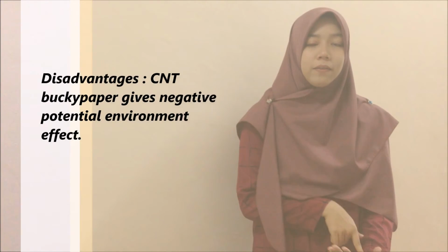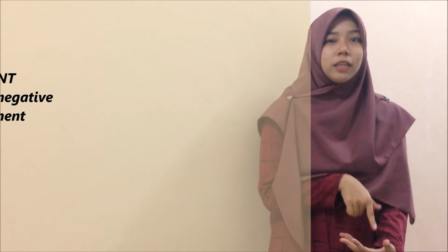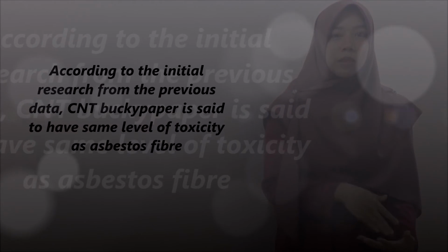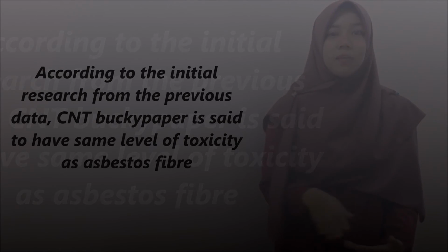Okay, now I will move on to the disadvantages of carbon nanotube Buckypaper. The first disadvantage of this product is that it has a negative potential environmental impact. As we all know, this is a newly developed product, so we lack information about the shape and the size of this product that we need to determine the level of toxicity. According to initial data from previous research, carbon nanotube Buckypaper has the same level of toxicity as asbestos fiber, which is dangerous for us.